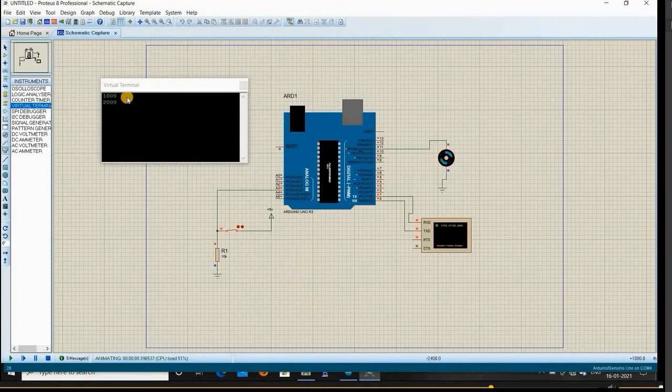After switching on, the motor is running and it will run up to 20 seconds. We can see the time limit there. The motor is running up to 20 seconds. Suppose in the middle the power has gone, the time will be held at the 11th second and the motor is in off state because the controller is not passing the signal. And then later I switched on again, meaning power has come. Then the time starts running from the 12th second from the resumed state, and it will continue up to 20 seconds.